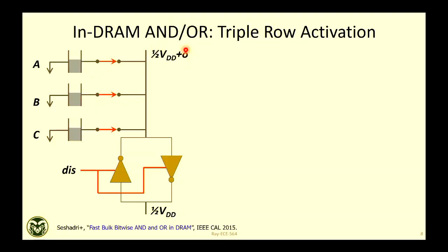Because it is delta, your answer will be 1, because now the sense amplifier, right? One other end of this amplifier is fixed, which is half VDD, always fixed. So if your bit line, sensing bit line is a little bit more than half VDD, sense amplifier will make it 1, right? So next step will be, it will be VDD and this will be 0. So you are getting your output result as 1.